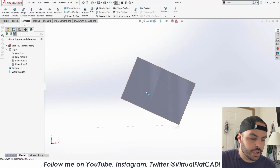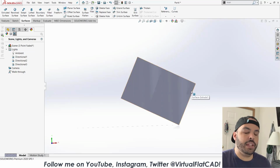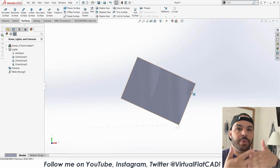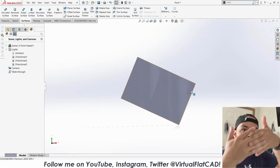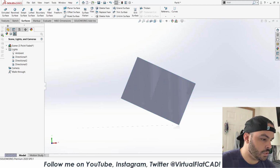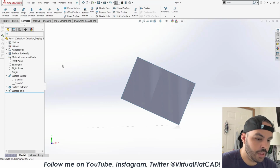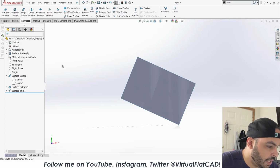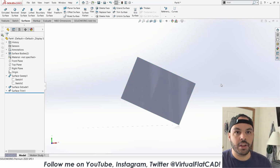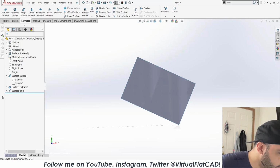Okay, so in order to make a checkered flag, I could put a texture, but I do find that sometimes when you're wiggling around a surface like that, if I put a texture, it tends to shift around the surface, and it kind of breaks the illusion. So I might not go that way, but what I'm thinking is I might split up the surface into faces and then color them with appearances.